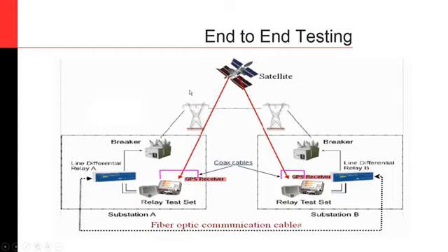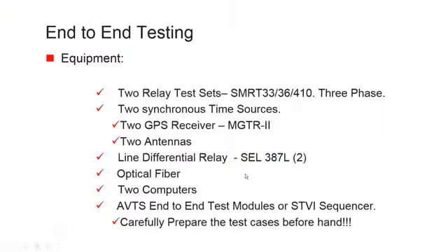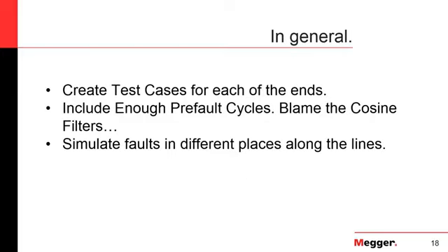Now, when you're talking about synchronization using the power system, what it says is that the frequency of the system is the same in all places of the system. But it doesn't mean that the power system has a common time source or anything of the kind that I can use to actually know when to begin the test at one end of the line or at the other end of the line. This is what I mean when I talk about synchronization. I don't know if that's enough as an answer or if I should talk a little bit more.